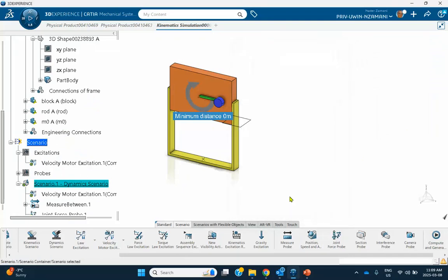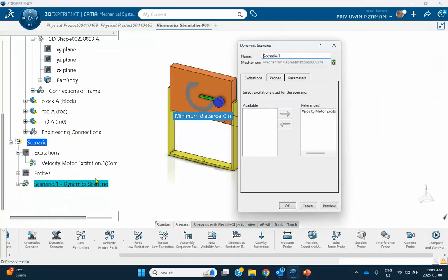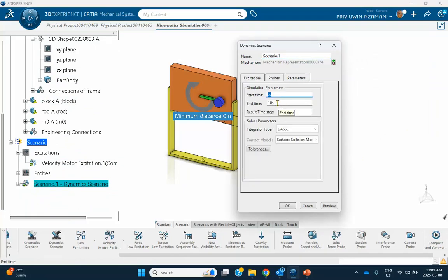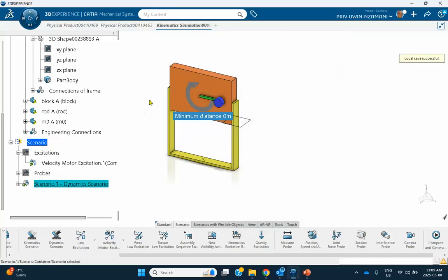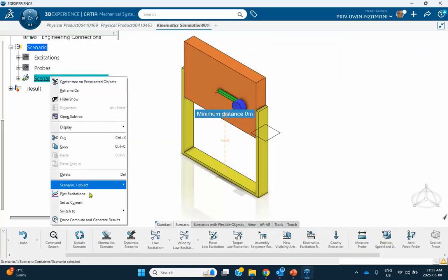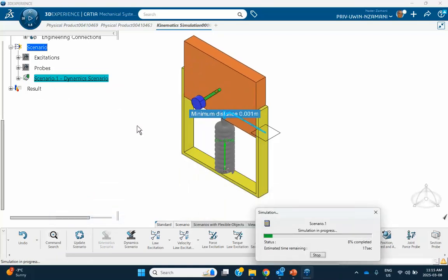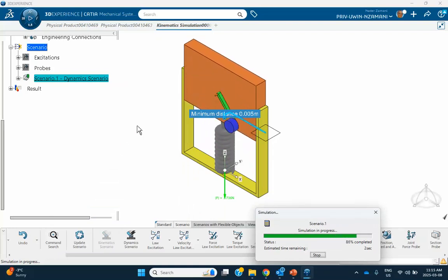Yeah, it's already included. Now, as far as the duration is concerned, I click on that tab, we put down, sure, 10 seconds, and 0.01 is fine. We say fine. The integrator that we're going to be using, and let's go ahead and run this thing for 10 seconds.